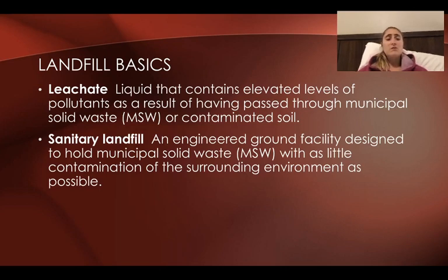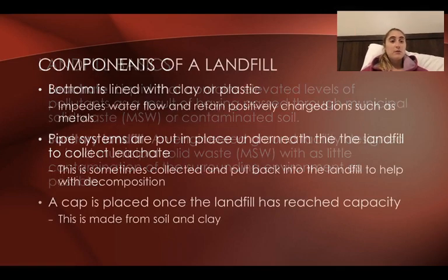And one of the ways we do this is through the process of a sanitary landfill. And this is what most landfills are now, but these are landfills that are designed to hold municipal solid waste without contaminating anything around them, to make it so that there's the least amount of contamination possible surrounding the area around that landfill. So that is all to prevent any leachate from ever getting into water or soil or near people in that area. Okay, so now that you know those terms, we'll move on.